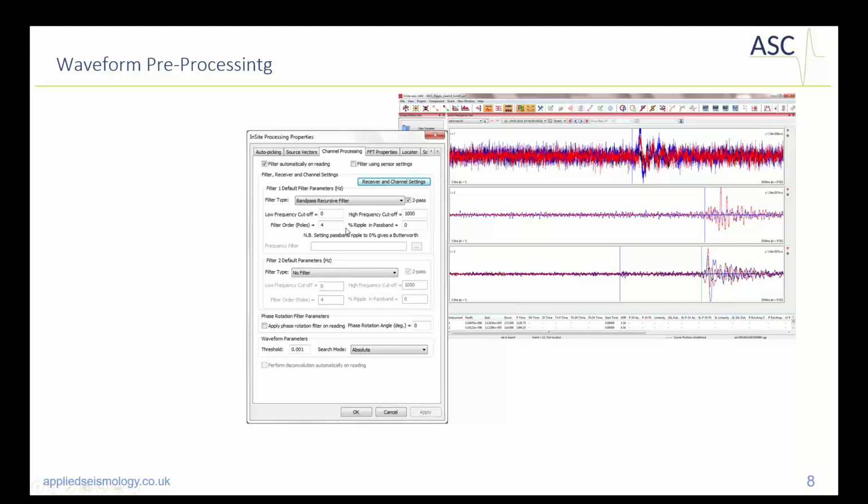But also we typically need to clean our data from either interference from electrical equipment or noise that is inherent to any experiment. We are breaking rock, so there's some friction in the plates, etc. that can induce some noise, typically of a very low frequency. So we typically need to apply a filter so that our arrivals are clear. And this would be the first step.